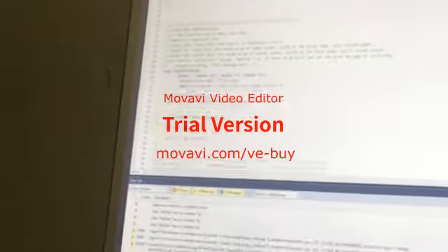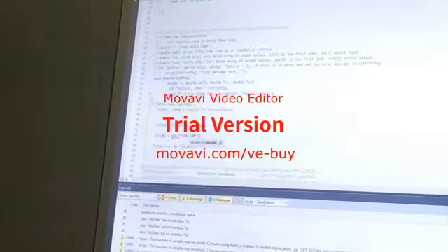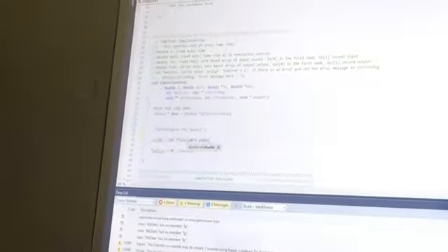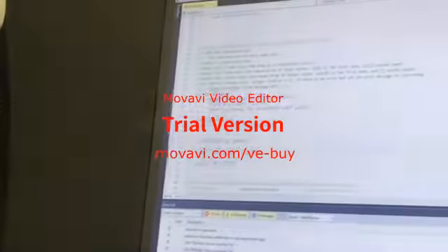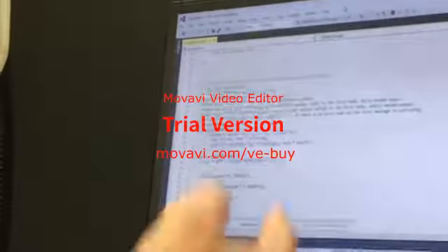Okay, out is going to be 169.7 times, because that's going to be the 120 volts RMS, right? Times sine of 120 times 3.1415, whatever, times time. It doesn't have just a variable PI, like pre-programmed? You might. Okay. That's pretty accurate.